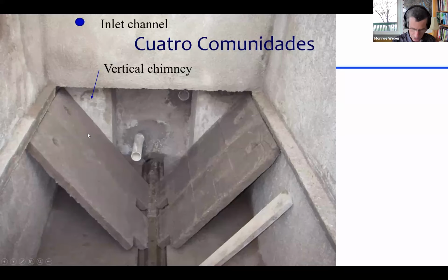bottom. So this is where the water travels. It goes down the chimney, then it pops out of a hole underneath those slope pieces. It comes up through the port that was at the very bottom of the sedimentation tank that these slope pieces create. And it looked just like, this is a wonderful design. But maybe you're already thinking you see some problems with this based on what we've been learning. So let's look at what actually happened.